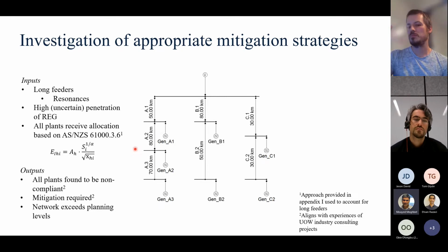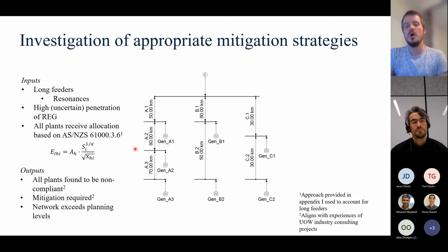Thank you. And would that filter be enough for the whole network? Yeah. What we can show is that if we connect a filter at the point at which the impedance is the highest, ultimately you've unlocked a bit of headroom, so that you can have a higher amount of emissions. Depending on your filter and your network, you may find that your planning levels will be reached with an increased amount of harmonic sources present on the network. It may also result somewhere else now, because this is no longer the highest impedance point on the network, so it may be occurring here or here, somewhere else.